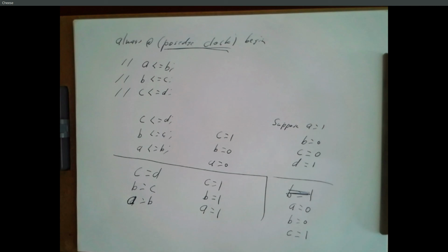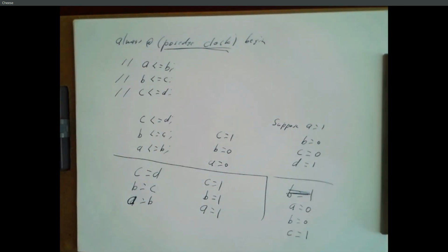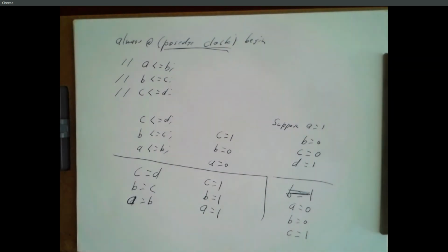And the compiler won't mention anything to you about this, right? But this is definitely doing something different from this. So best advice, never use blocking equals assignments inside an always block, right? Always do this non-blocking assignment.